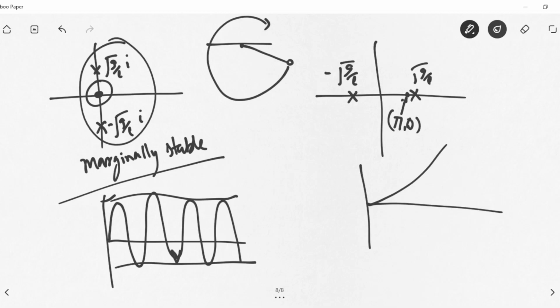With respect to nonlinear systems, that's what the case is. Our system is not simply stable; our equilibrium points are stable or not individually. You have one equilibrium point, 0 0, that is marginally stable, and another equilibrium point, pi 0, that is unstable. It has an eigenvalue in the right half of the S-plane, and therefore this represents an unstable system.